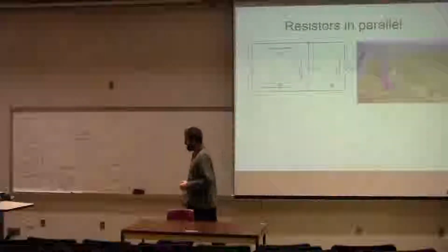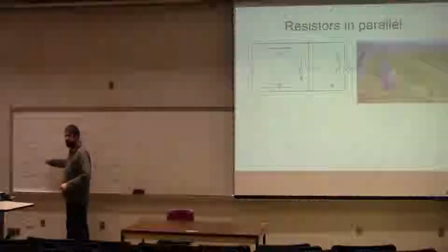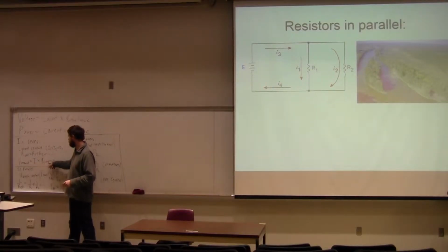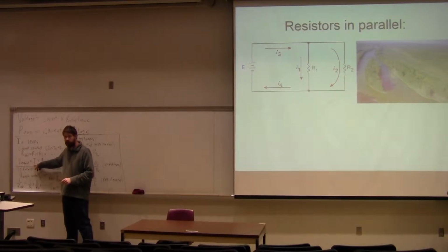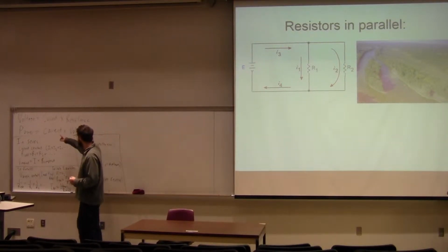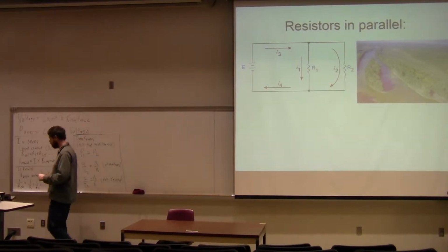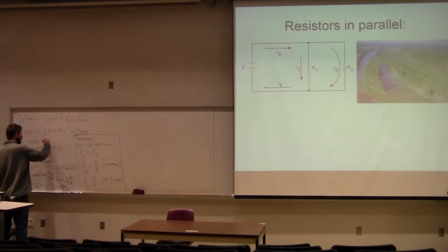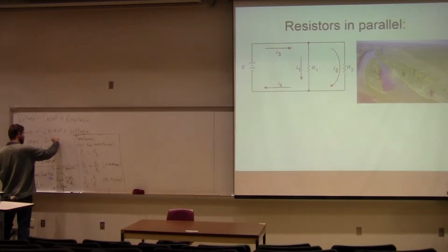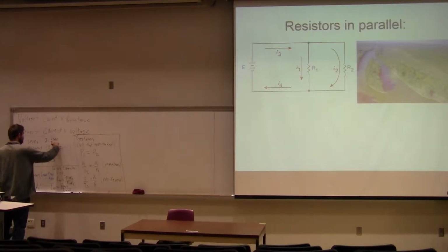So in this case, instead of adding up the resistances, and by the way, voltage component always equals current times resistance component. Notice I didn't put current component because in series the currents are all the same. So I don't have to worry about that, just whatever the effective current is, where the effective current was equal to the voltage for the circuit divided by the resistance for the circuit. So maybe I should write that down. I equals voltage total, so the battery voltage, divided by R effective.